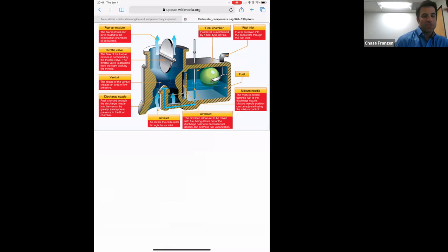All right, so I'm just trying to get through as much of systems as possible. I've explained the power plant system. I've flirted with the fuel system. So let's explain the rest of the fuel system here. As I mentioned, the thing that's on the screen is the carburetor. This is the thing that controls how much fuel and how much air together goes into the cylinders to then create the power, and as we talked about, the 4 strokes of power. So this fuel inlet on the top right.